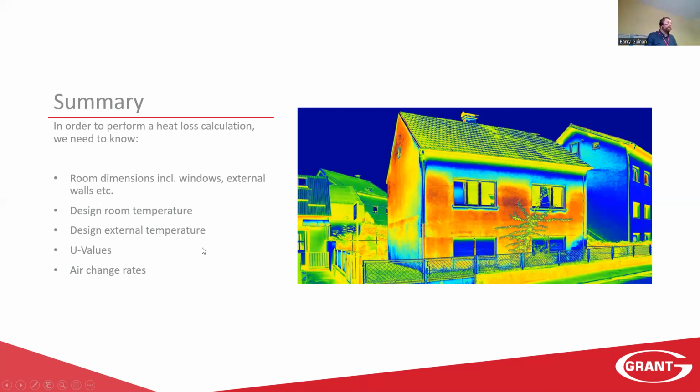We need to know the U values of all the different elements. And then we also need to know the air change rates. So once we have these bits of information, we should be able to perform a detailed heat loss calculation.